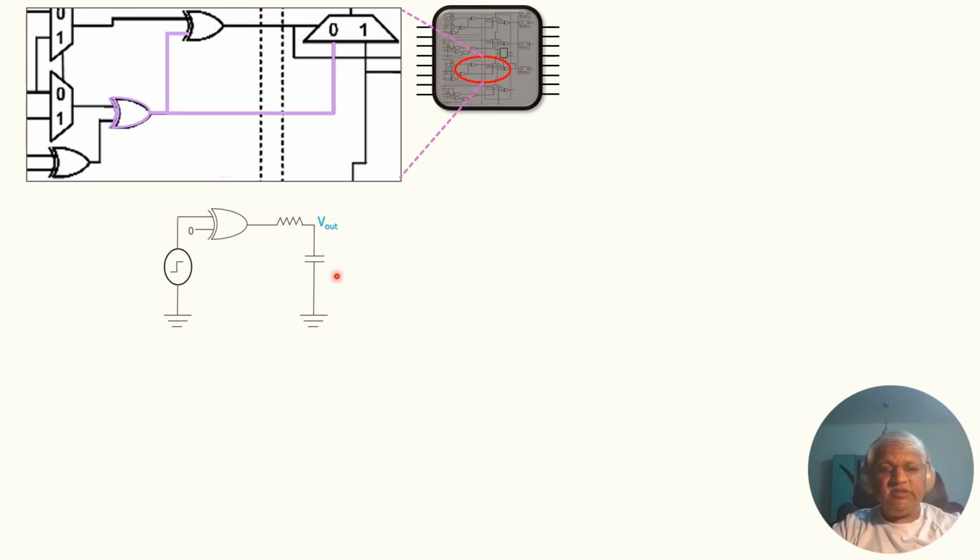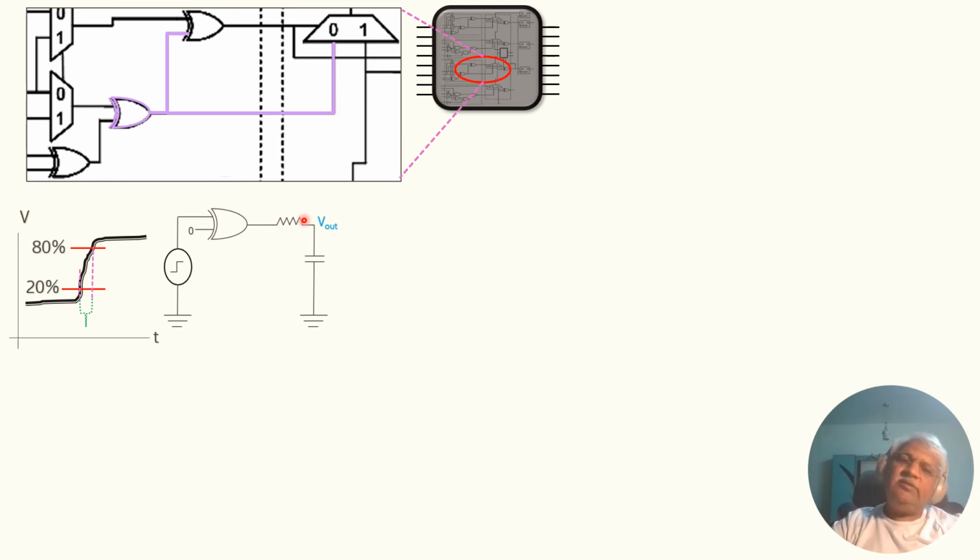Now if you see this circuit which we are analyzing, for simplicity I have considered the other input, which is this one, to be 0. Now, this net and the associated capacitance is represented in a lumped format as R and C. However, in the actual SPEF file, which is the standard parasitic extraction format, the representation of the nets, you will observe that it is a distributed resistor and capacitor.